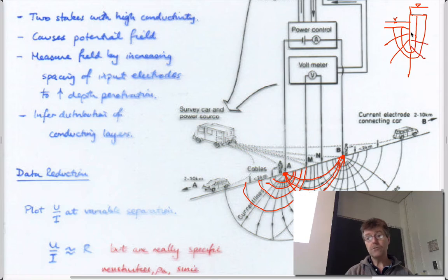Did you draw flow nets, by the way, in 432? Yeah. So each of these lines here would be flow lines. This would be the pathway that particles of water would go. This would be an equipotential given by this measurement of the head here. It would just be equal to this elevation here. This equipotential here would have the elevation of this head here, and these would be equal drops in potential. So these are the same.